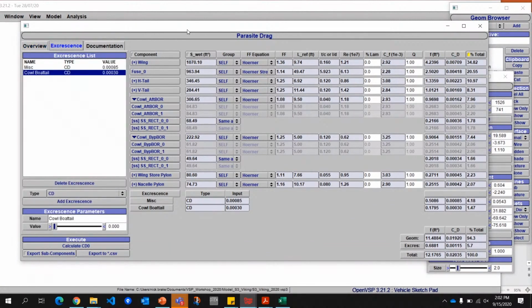However, the one really great thing about the one built into VSPAERO is when you're doing something like rotating blades on a propeller or a rotor, it's able to calculate that local velocity and local Mach number and local drag as the velocity varies out the radius of a blade, and calculate that drag so that it actually increments the power required of the rotor, based on that Parasite term, not just the induced term. And that's of course something that you wouldn't even be able to get out of a normal airplane analysis for that Parasite term.